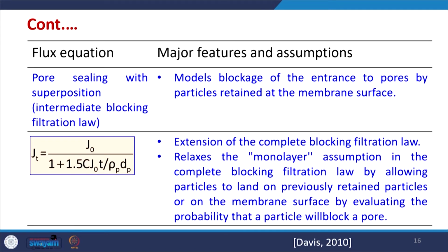Then there is a third type of model, which is also called the intermediate blocking filtration law. So, in this case the pore sealing with superposition is assumed, and in this model the blockage of the entrance to the pores by the particles retained at the membrane surface is modeled.